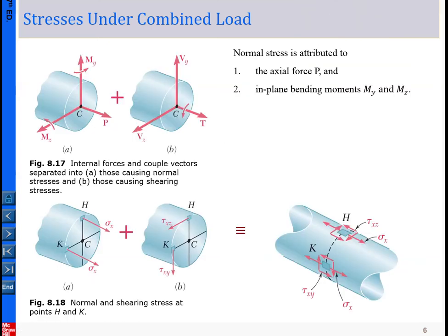And so here, before we move on to the quantitative analysis, let me give you again a general guidance about what could be involved in our calculations. So the normal stress, the first one, will be coming from two possible situations. One is axial loading P. This one will give us the normal stress, and that one is actually equal to P divided by A.